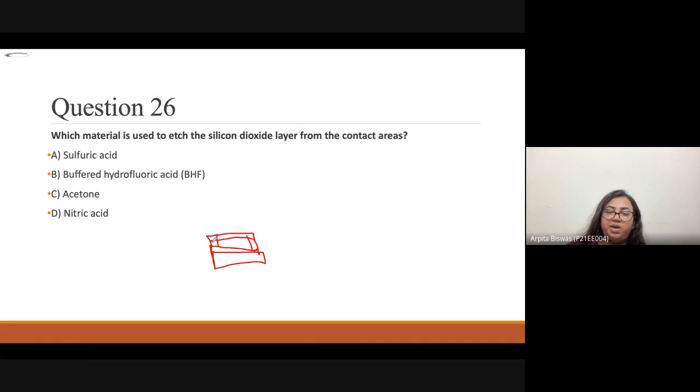This portion is the micro heater pad, and we want to remove the silicon dioxide on the micro heater pad. So this is the silicon dioxide layer, the SiO2 layer is present. So what we will do, we will coat it with the photoresist, and we will go for the lithography process. Okay, so if we go for the photolithography process by using the photoresist and the mask pattern, then after the UV exposure, we go for the development. So this portion will be removed.